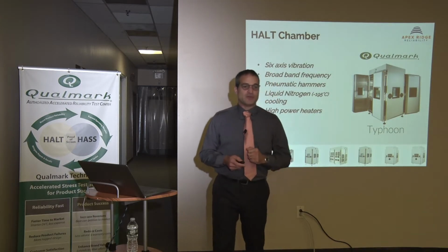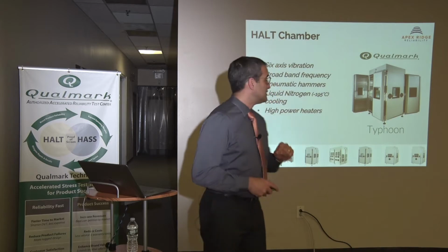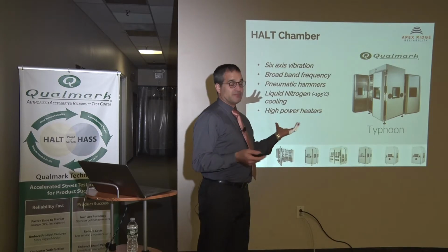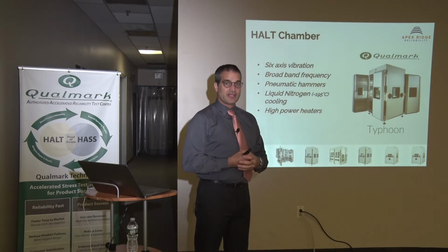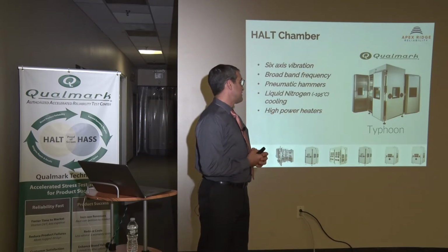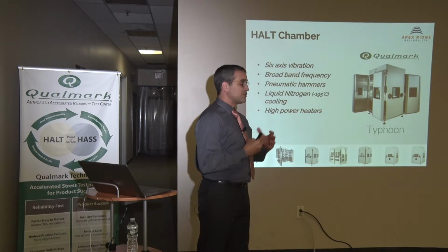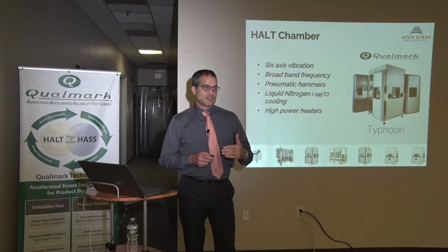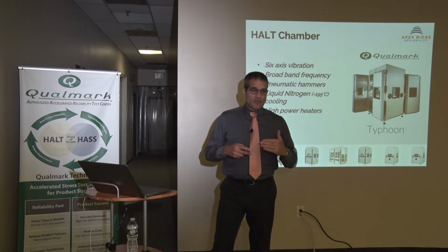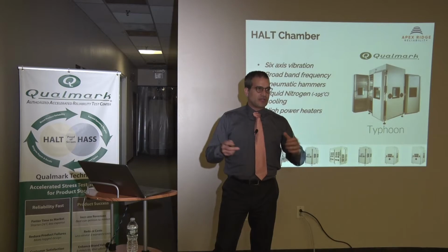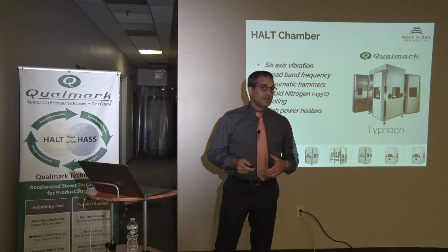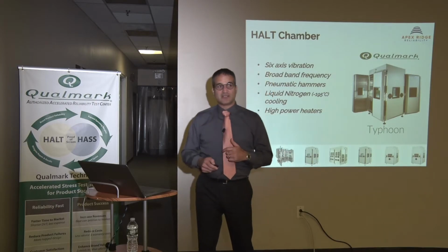So the equipment. A lot of HALT testing is done in a HALT chamber, and Qualmark has always provided them. They're really the creators of it. Dr. Greg Hobbs, who created the HALT method, is the founder of Qualmark, and they create chambers that produce the vibration and the intense temperature swings that are very commonly used in a lot of regular product development. And by having a tool like this, you can do these tests very quickly, usually within about 3 days, and yield a great deal of information.